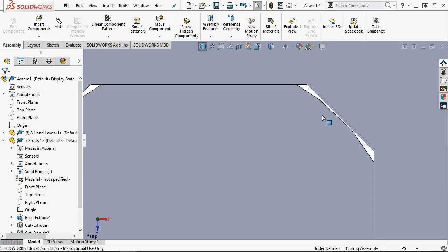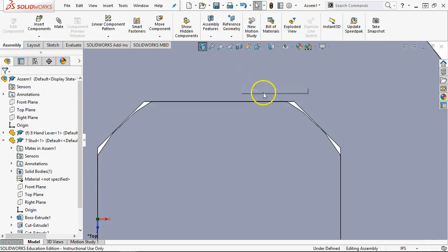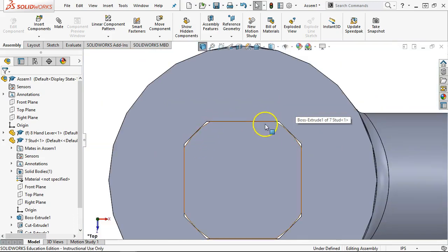Which is going to cost more, to take a circular broach and put the flats on it, or take the square broach and put the rounds on it? All right, but the main thing is that with the gaps, this is still a relatively tight fit, and there's enough contact surface over there that I'm really not concerned.